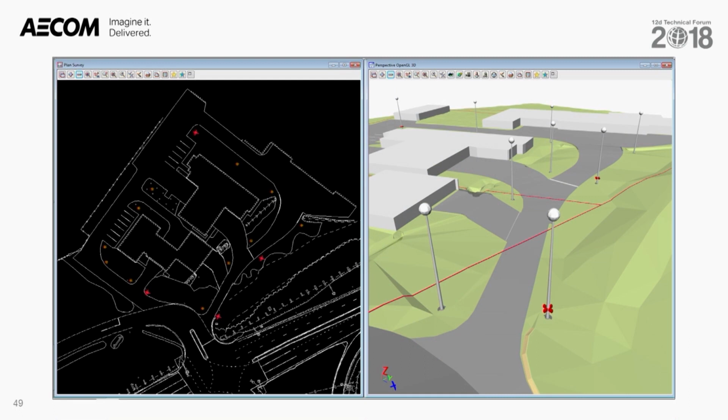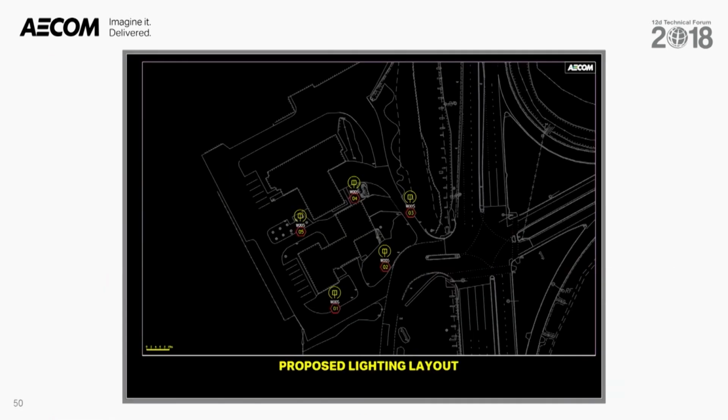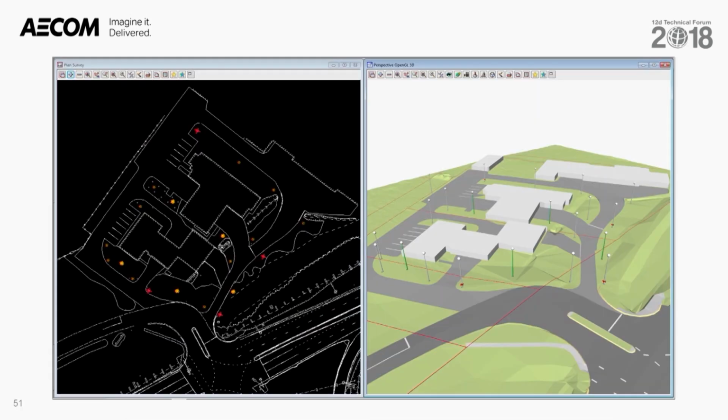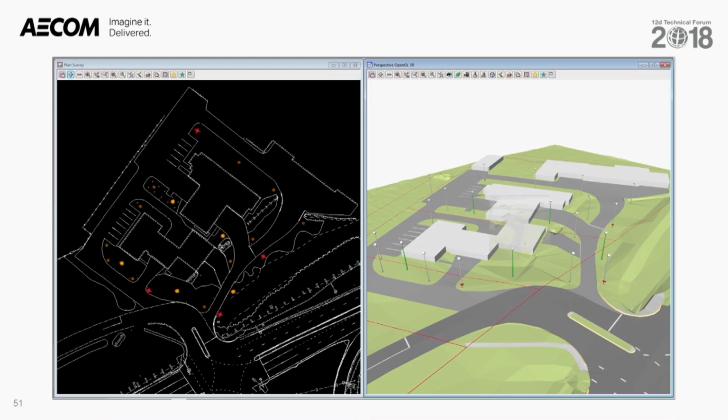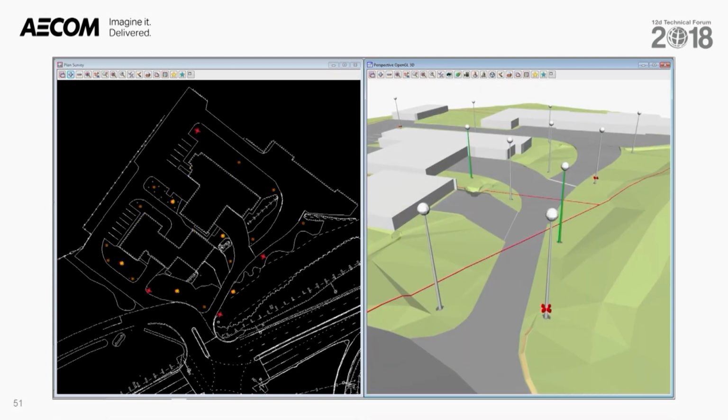For most utilities models, this process of identifying those to be removed is a manual one anyway that evolves to match the changes in the civil design. The source of information for proposed utilities, or even for dial before you dig layouts, is usually from a 2D AutoCAD drawing that's read into 12D. The vertices are these points draped onto your supertin surface to assign either design or existing levels to the points, and then mapped to solid objects using exactly the same process.